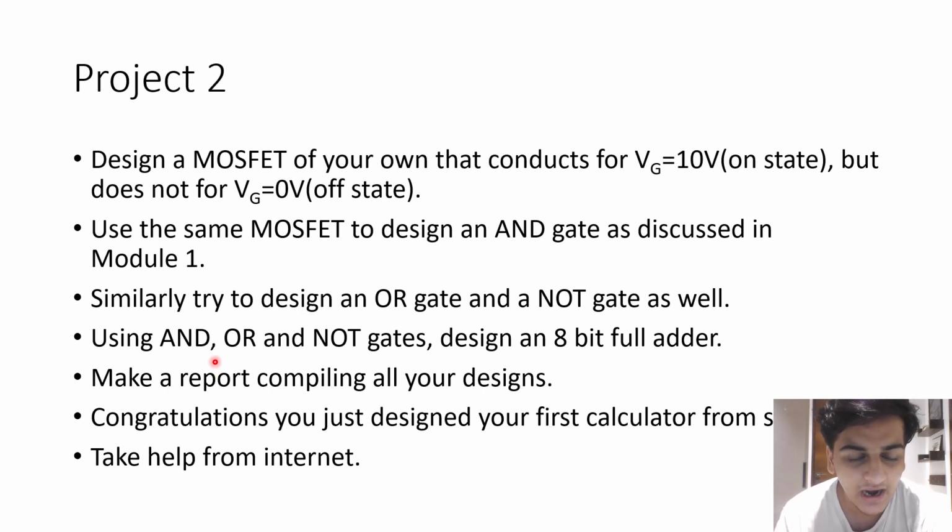Finally, you use AND, OR and NOT gates to design an 8-bit full adder. You make a report compiling how you design the MOSFET, how you use that to design the gates, and how you use the gates to design the adder. And I guess you can claim that you've understood and designed your first calculator from scratch because you designed something that can on hardware implement one calculation based on the inputs given by any keystrokes, right?